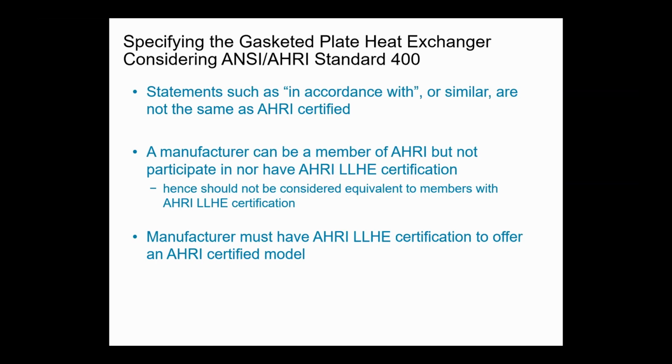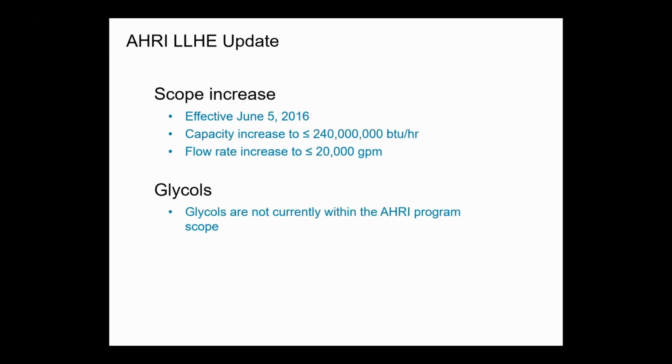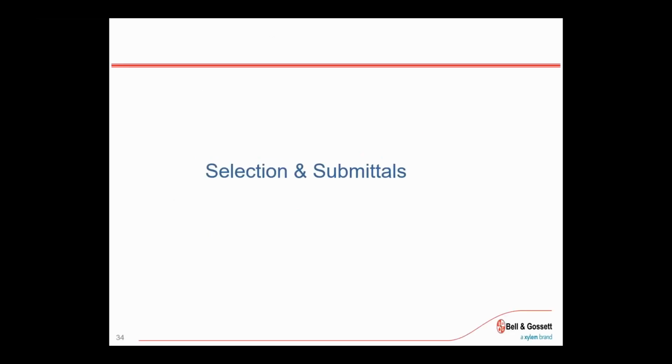Like what I was saying with heat pump chillers, for instance, people might use 550, 590, that's for the chillers. If you look at all the manufacturers, they'll say tested in accordance with, but that's because there isn't a standard specifically for it, because it has a heat portion. So the best that everybody can do, to be honest, is to at least test the chiller portion to it. But if there is a standard out there that is third-party verified that a bunch of manufacturers have joined, then it does make sense to list it as a requirement rather than in accordance with, if something hadn't been established. Okay, yeah, it was some time ago that that became the case.